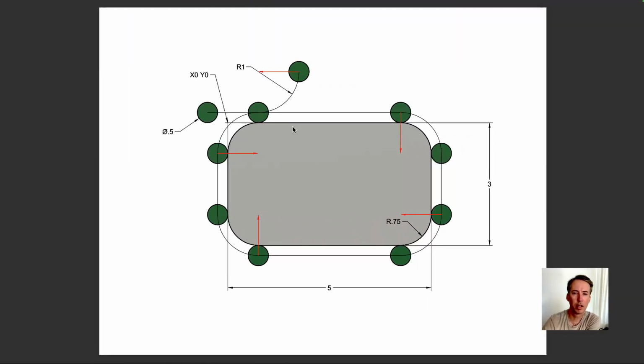And then if you look at this block, so I gave you some outer dimensions, and then I gave you a corner radius. So all corner radiuses are the same. It's 0.75. So if you think about this, if the radius of this arc is 0.75 from the origin here, it's also 0.75, because this is a 90 degree arc. So from here to here, 0.75. So in absolute, that's X 0.75.